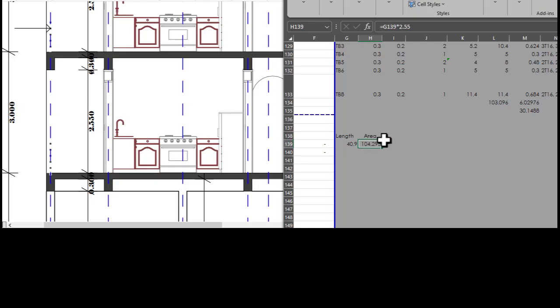This is now the gross area, okay. But then when you refer to our standard methods of measurements, you need to realize that we are supposed to do that area as a net in the sense that we need to deduct the openings, okay. And for the internal walls, the openings that you have are normally the doors, okay. So you have to ask yourself, where do you get the sizes for the doors, and how do you do the deductions? So it's simple.